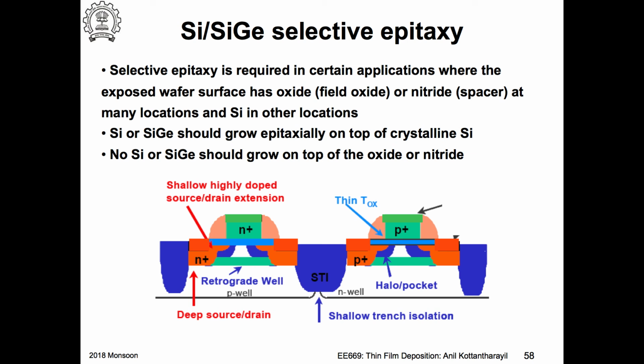So you need to go to high temperature. Let's say 900 degrees centigrade. But once you take amorphous silicon and expose it to a high temperature ambient like 900, forget about 900, 700, 650 and onwards, it starts to crystallize, but it will actually form polycrystalline silicon. So you would form polycrystalline silicon here, monocrystalline here, polycrystalline here and so on.